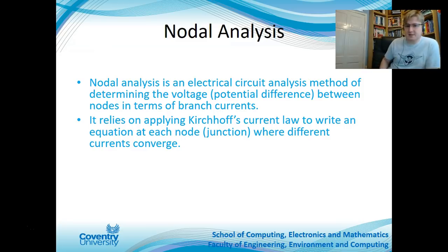Nodal analysis is essentially an electrical circuit analysis method of determining a voltage based on the potential difference between 2 points or 2 nodes in the circuit, hence the term nodal analysis. It relies on being able to apply Kirchhoff's current law to write an equation at each node. So it's like mesh analysis.